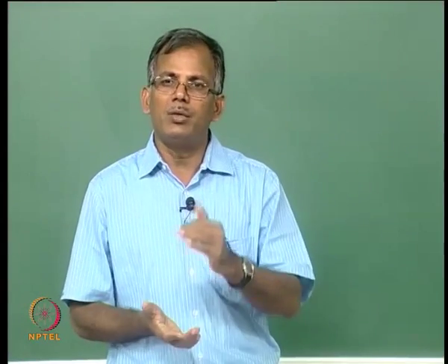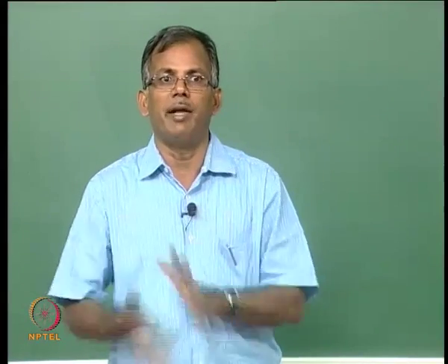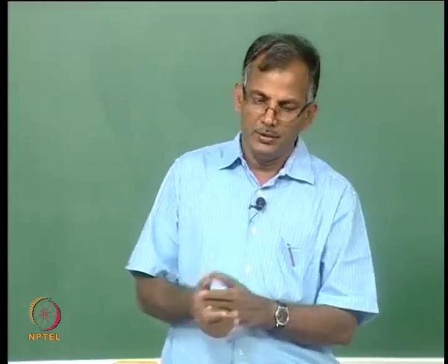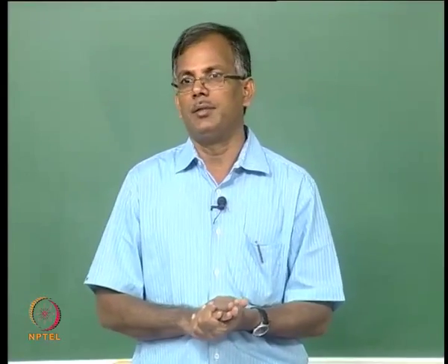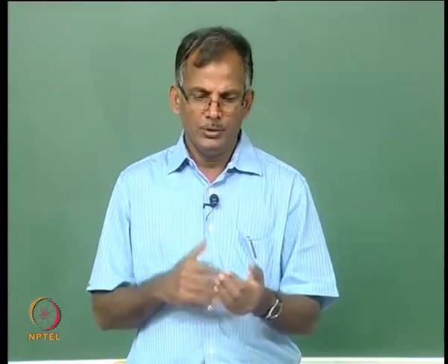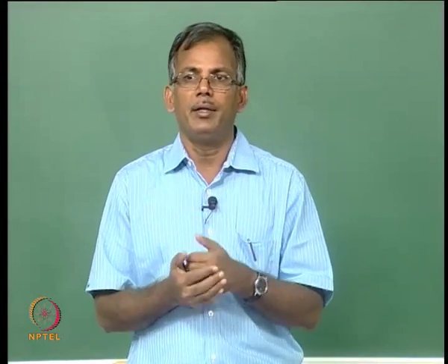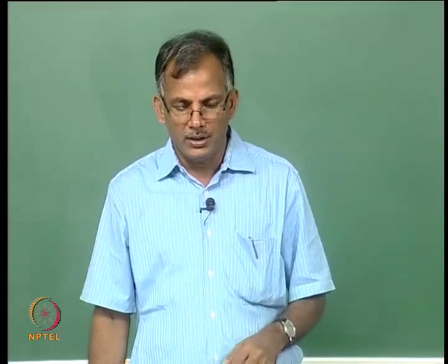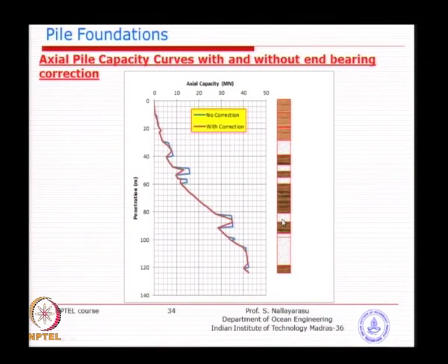during slight overloading of the structure, punch through can happen and the pile fails. Now, to avoid that, we need to have a minimum layer depth, the pile must have gone a minimum distance inside the layer itself. So, that is the reason why, if it is a smaller layer, we cannot consider the full capacity, we need to downgrade the capacity of that, so that we are on the safer side. So, that is the rule that we want to apply. That means we need to downgrade the capacity something like this. You can see here in blue color is no correction, the red color is with corrections.